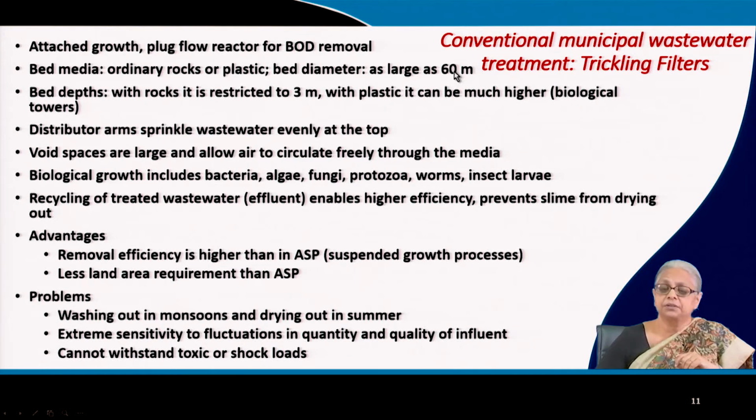The bed diameters can be anywhere from 30 meters to 60 meters, or even smaller. So bed depths are restricted. If you're using rocks and stones, the depth cannot be more than 3 meters. But with plastic towers, which are called biological towers, these plastic biological towers can be very, very high.